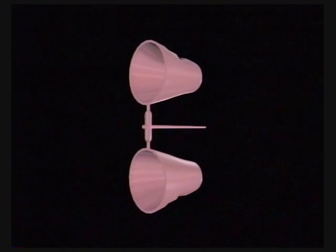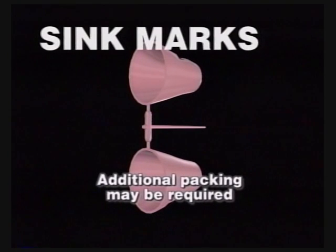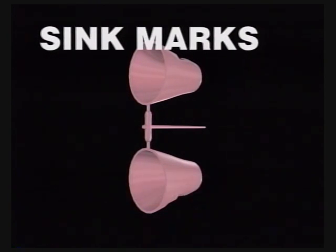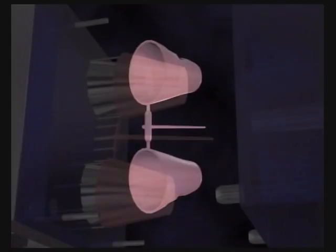Sink marks may be caused by a number of processing oversights. Assuming the sink is not the result of a poor part or mold design, additional packing may be required to fix the problem. Check the shot size first to make sure that it is sufficient to fill the part. Injection pressure or injection time may have to be increased to allow for more packing.